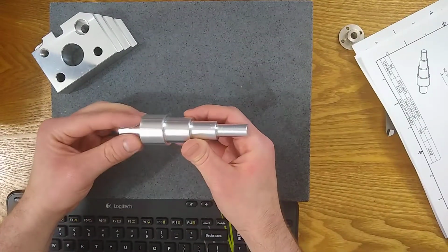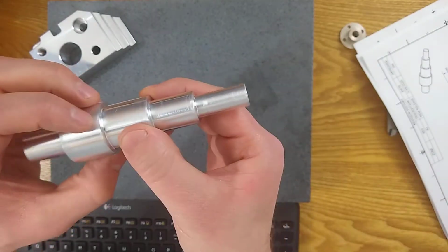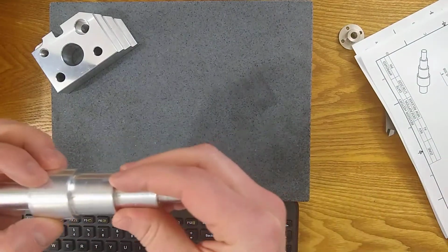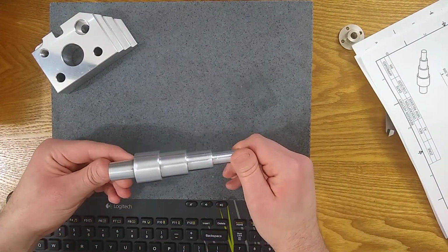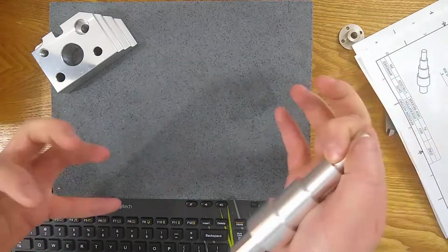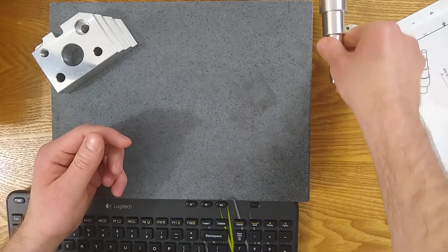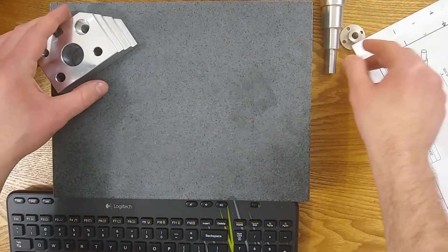Well, the GD&T standards will say, pick the largest diameter. You got to pick something, so it says pick the largest diameter. If it's not stated, your overall is your datum. So remember that. If you need to choose a datum, go ahead and pick the outside.